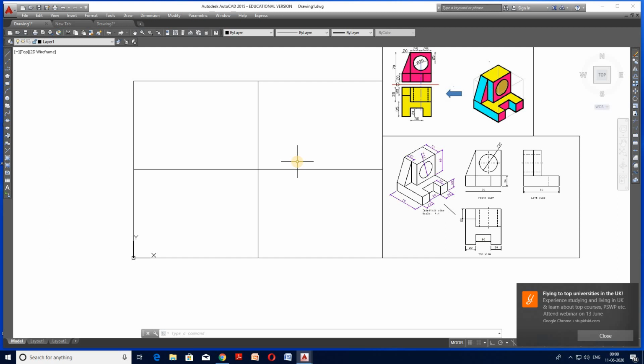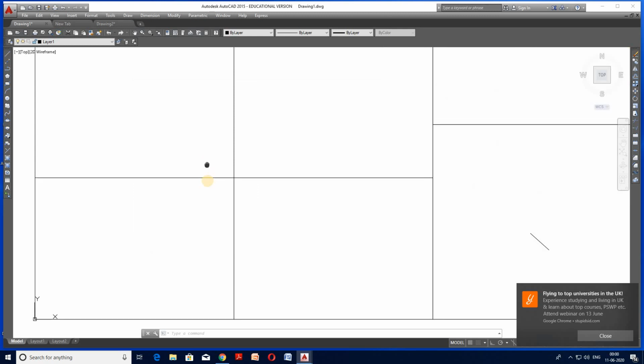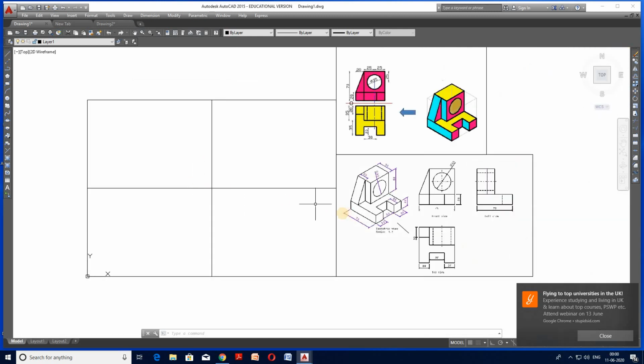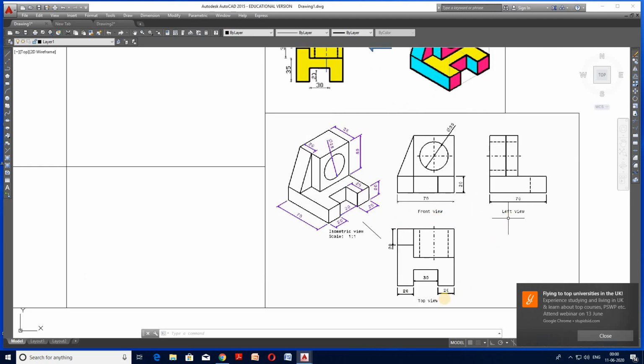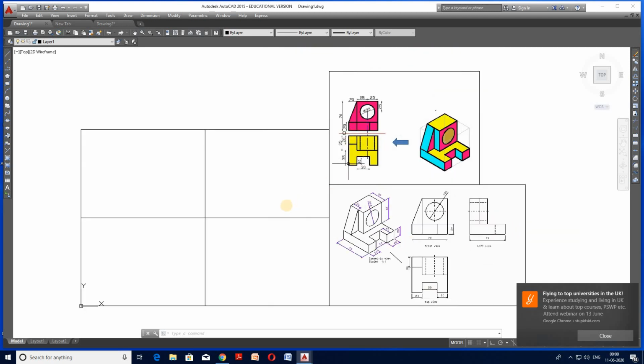As you know, there are 2 different methods, that is first angle method and third angle method for drafting. Here we are using first angle method for this case. So now start drawing, but before that set the margins. The importance of margin is you can write the title like front view, left hand side view, top view, and the dimension in that particular margin. So you keep some space from these reference lines with the help of margin.